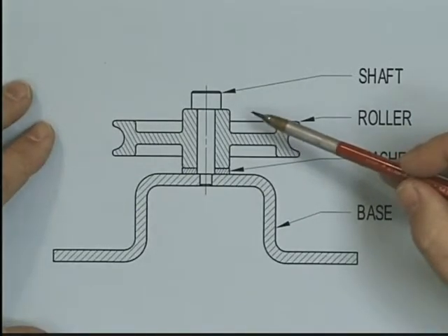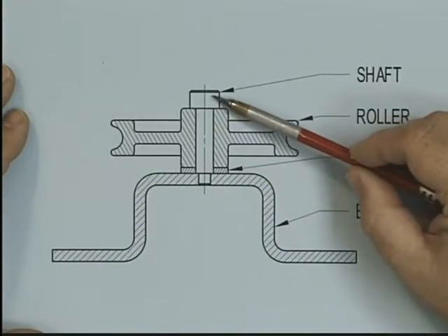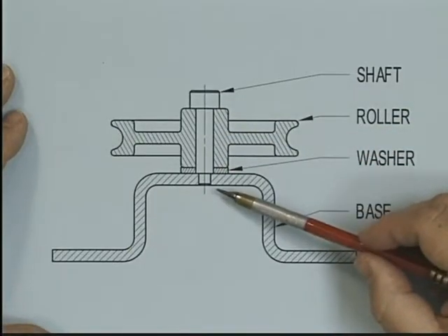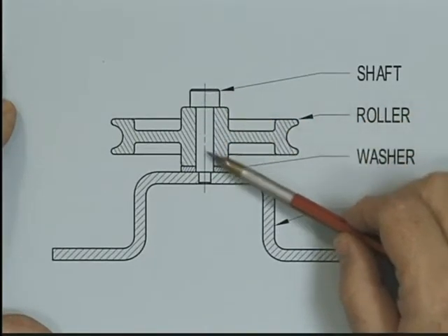Also, when we have standard parts, such as shafts or screws or other things, we do not put cross-hatching lines in those standard parts. So in this case, the shaft, even though it's cut by the imaginary cutting plane, is not cross-hatched. It turns out that along with the section view business, you have a lot more to learn than just the 3D visualization necessary to imagine how these imaginary cutting planes cut through objects and how they look. There is a whole book full of conventional representations, and you not only have to learn the section view process physically, but you have to learn the vocabulary and the conventions that are used to demonstrate these different types of sections. Let me show you just a couple more of these standard section view conventions.